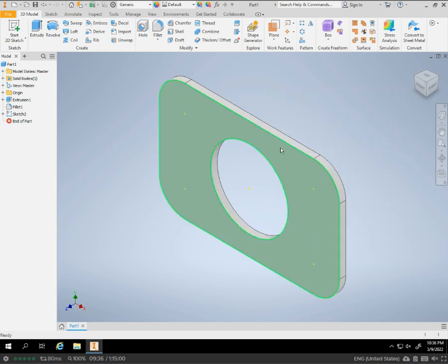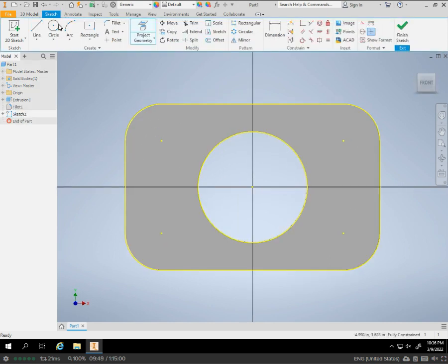All right, so we're just going to cancel that. We'll just use circles for right now because I don't want to spend a whole lot of time trying to do that. So in order to use the circles, we're just going to double click on sketch number 2 and quickly do it with that. The hole tool, I'm going to play with it a little bit longer since it's changed in this new version. And we're just going to do 0.75 for each one of these circles here. And we'll just do all 4 of them.